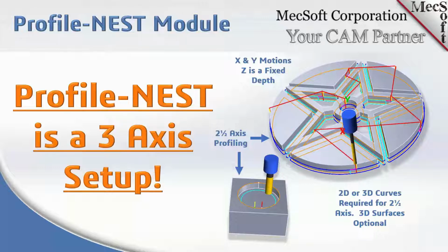Okay, so each part you will set up to program a 2.5 axis profiling operation, and then when you set up your nest, your initial part will stay where it's at, and your profile operation is what will be nested.